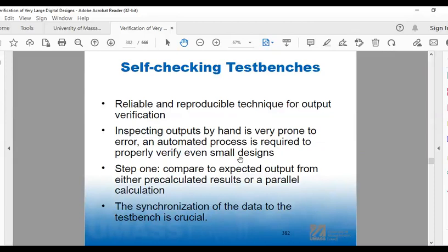And also, is the exact method of rounding that's used in that processor that predicted the output the same as the rounding that gets done? Probably not, because I use MATLAB and it's 32-bit floating point, and then my little digital circuit has 12-bit buses. And so when you compare them, you can't simply say, does that equal that? You might have to do is that within 1 bit of that or something like that.